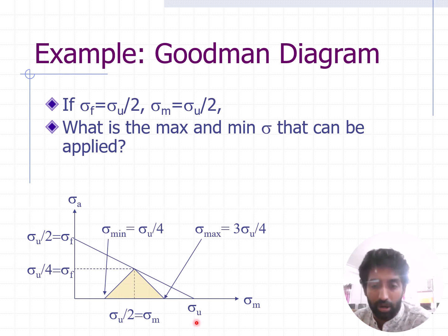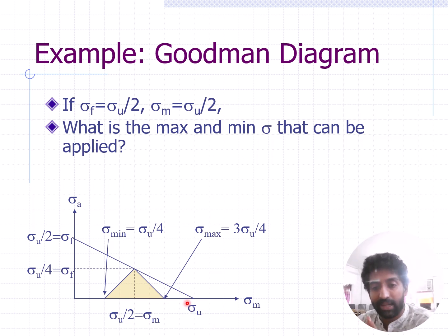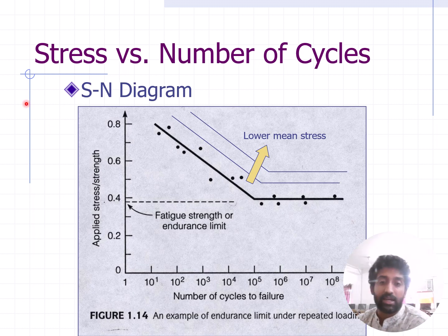not. That actually gives us a broad explanation, because this point may be your ultimate load zone only, under ultimate load zone, maybe not, I don't know. I'm just telling them. So if you get this opportunity or the broad spectrum, a Goodman diagram gives a broad spectrum to understand where it can break. So you have that envelope to rectify. So you could shift that curve by using better material, good material, good design, that could help you out.